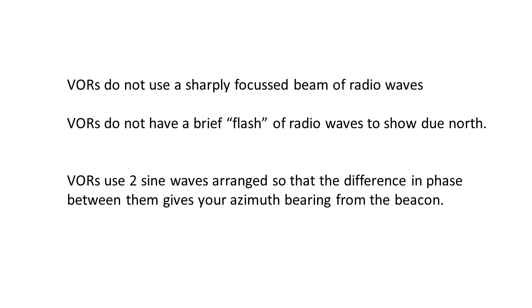However, this analogy has to be taken with a bit of care. The VOR does not use a rotating, sharply focused beam of radio waves, for example, and the north reference signal is not provided by a short pulse of radio waves. Instead, VORs send the data out using two sine wave audio tones, and it is the phase difference between these two waves which determine the radial bearing the aircraft has in relation to the beacon.